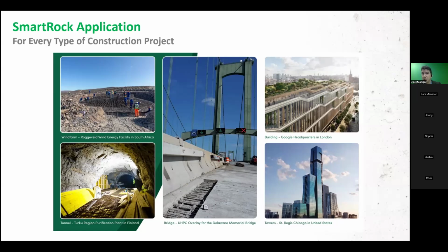It is a big deal because, imagine, the Hoover Dam, for example, took years to cool down. I'm talking about decades to cool down, because the volume is so big that the heat inside is trapped and doesn't dissipate. So what happens when you have a pedestal or even a mat foundation? Anything whose minimal dimension is 3 feet. That is the rule of thumb for mass concrete. If your lowest dimension is 3 feet, it means that it is massive.